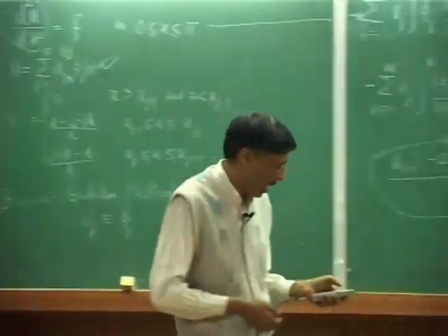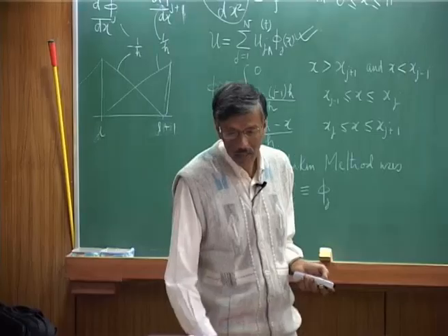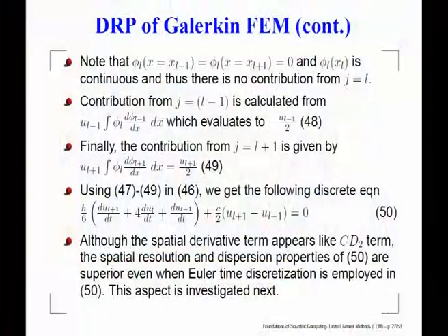That is where the footprint of the node is, from x L minus 1 to x L plus 1, and if we substitute it there, we will see that there would be a total cancellation, and there is no contribution coming from L. Okay. So, that is why we find that j equal to L does not contribute to that integral by any amount.